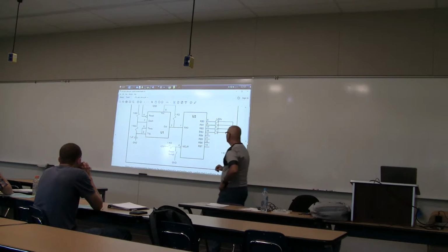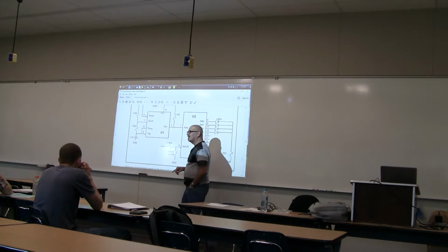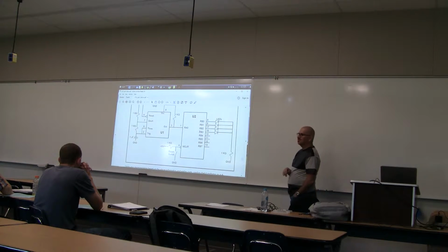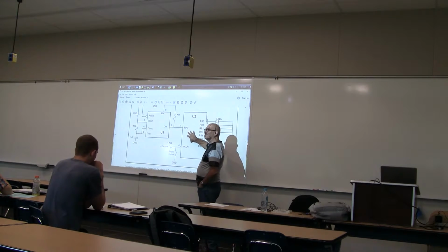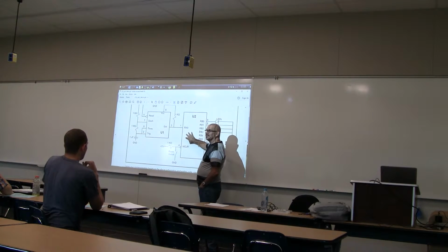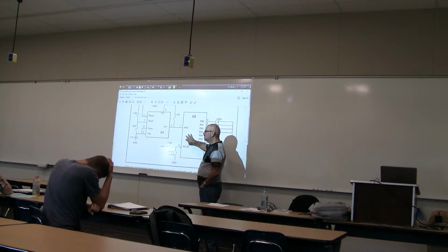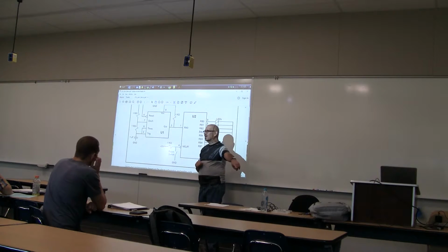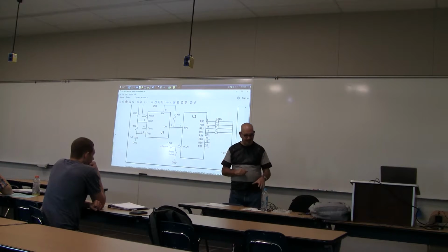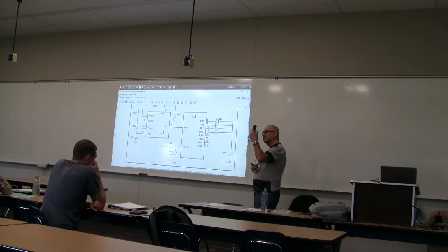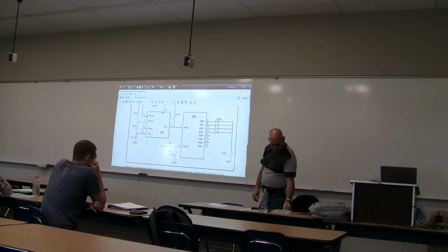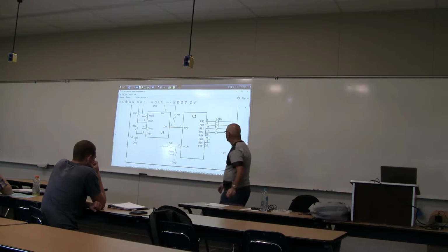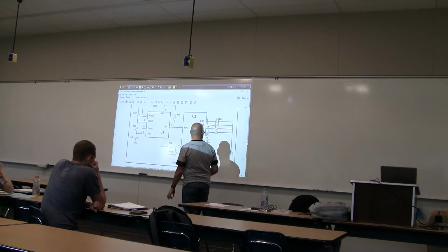On this PIC chip, pin 4 should be pulled high when you want to actually run your program. If pin 4 is low, the system is in a reset state, nothing works. If it's disconnected, it's unpredictable. But it turns out when we hook this up to the programmer, if we leave it hooked up to the programmer, we can actually get power from this as long as it's plugged into our USB port. And it will also control pin 4 correctly. But if you take the chip out and put it on a separate breadboard, we need to make sure pin 4 is going high.